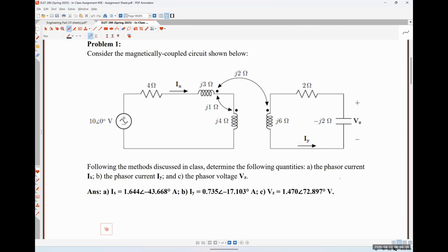So only when we see that double-headed arrow connecting the two coils can we say that they are coupled. So despite the fact that all three inductors have dots, we have two pairs of coupled coils. Okay. All right. So how I like to approach these types of circuits is I